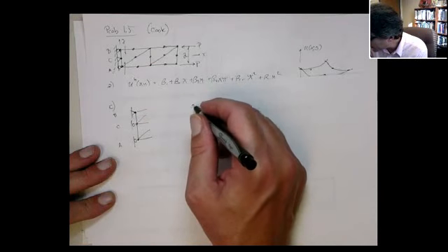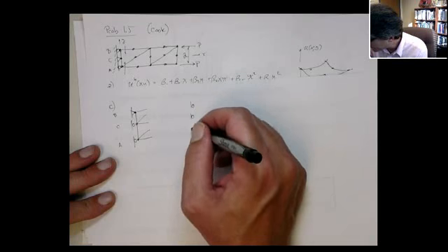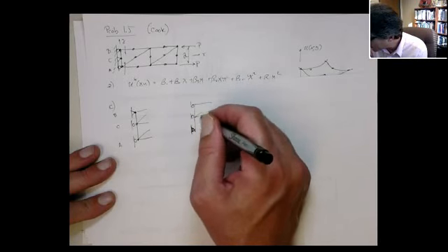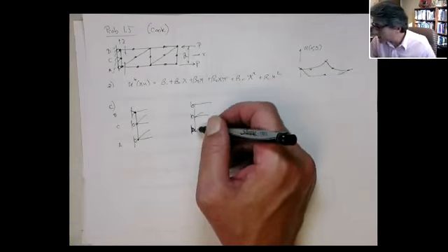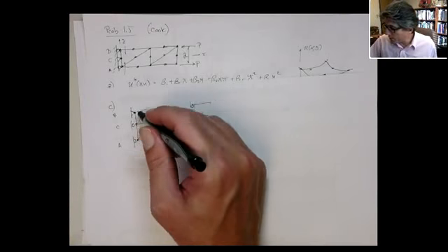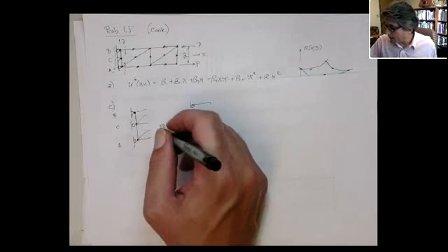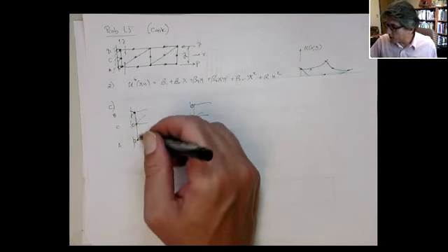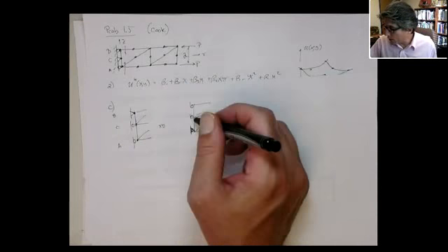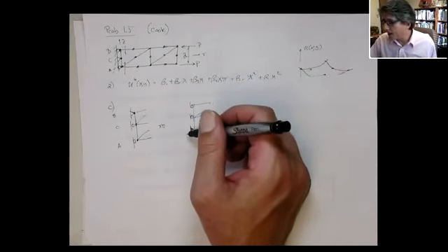The point is, oops, I put this fixed thing in the wrong way. This is fixed, okay? The point is, in all these configurations, you only fix one point completely at X and Y, and you allow the other two to smoothly move up and down in Y to contract freely. It doesn't matter which point you fix, okay?